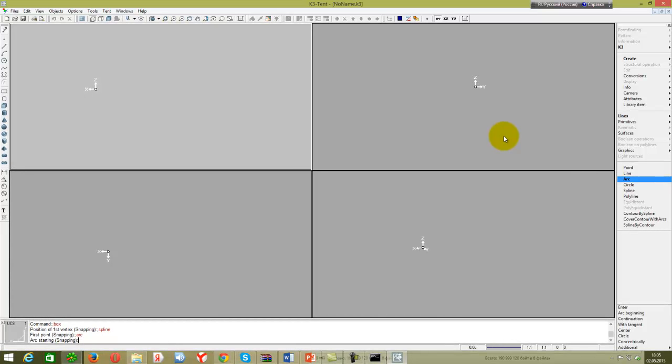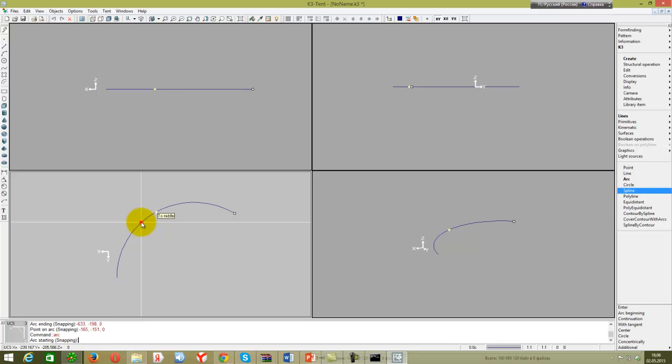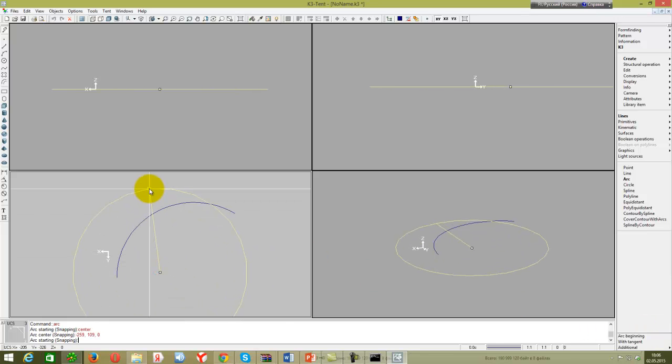We can similarly model arc lines, circles, and splines. To model an arc, we should define the coordinates of 3 consecutive points. By default, these 3 points are the following: starting point, ending point, and point inside of an arc. If it is necessary, we can define the center of the arc and 2 points on it: the center point, starting point, ending point.